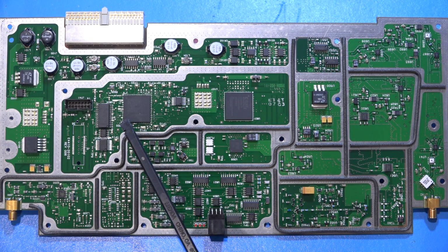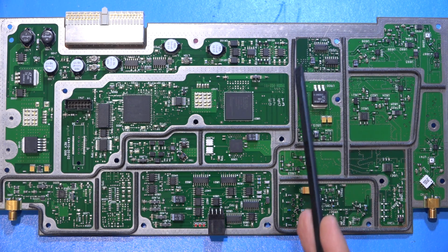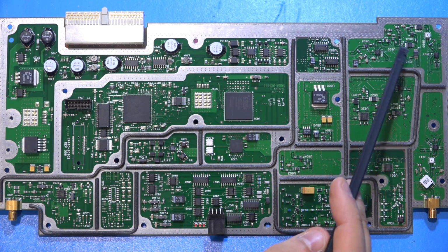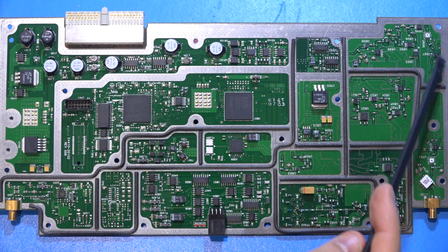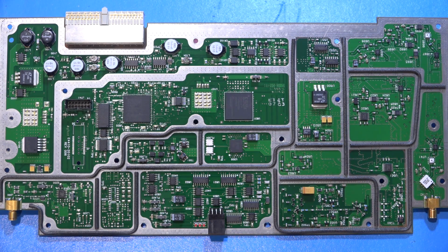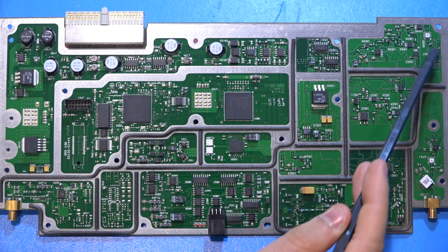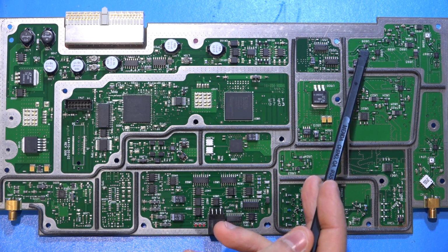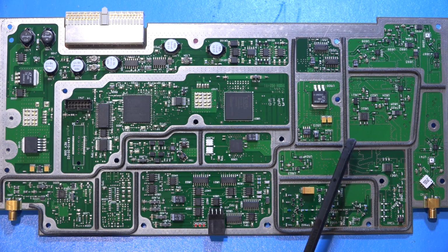So the path for the signal between the reference going through here and the VCO going all the way through here and all the way back out here is now known. So that's how the loop of the PLL is closed. After that, everything else is open loop. The next multiplication stages and selectors going to the output have nothing to do with the PLL anymore. It means that if something is broken here, this PLL wouldn't know about it because the feedback is taken before that part.